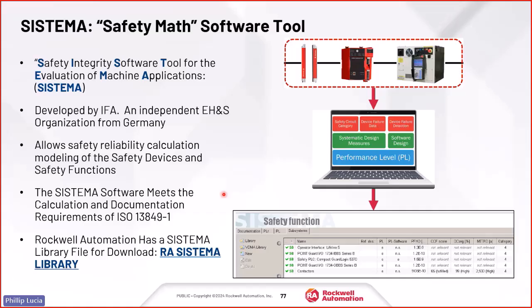And then I mentioned this safety math, these calculations. There's a tool called SISTEMA, which is an acronym, and we provide a library file for our safety related products so that these calculations can be done in perhaps minutes or less, versus maybe an hour or more to do it manually or having to look for the data in other places. So again, a tool to be aware of and something we can help